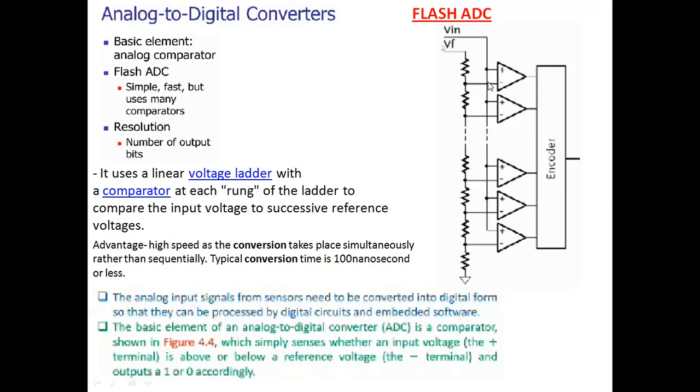According to the figure, you can find here a series of resistors used. This forms the MSB and this forms the LSB, which is connected to the ground. The resistor nearer to the reference voltage is the MSB, and this is the LSB. We have used a series of resistors forming a voltage divider network.